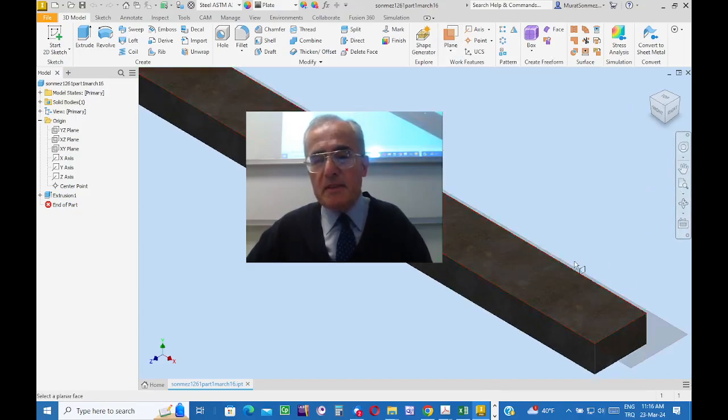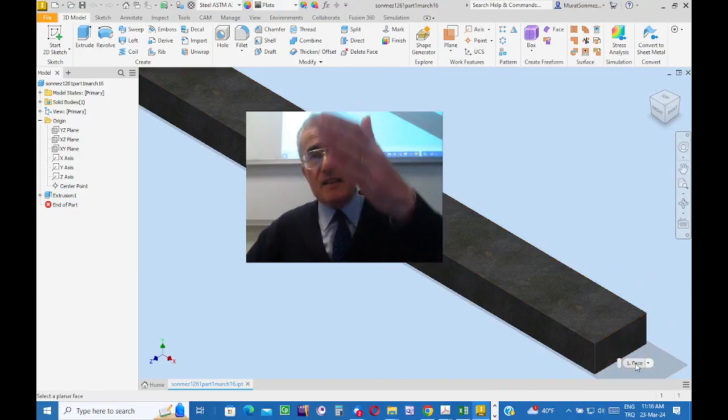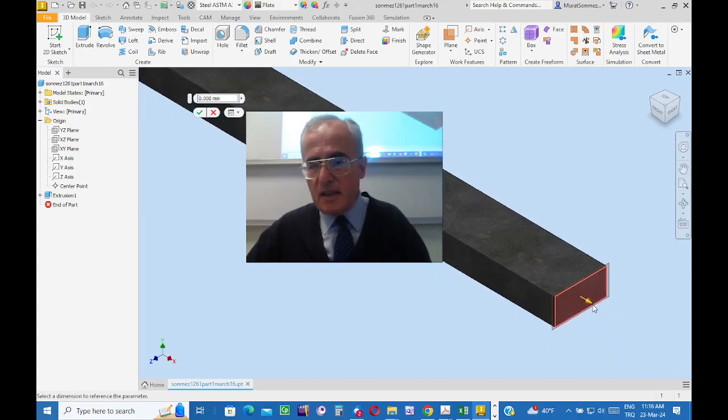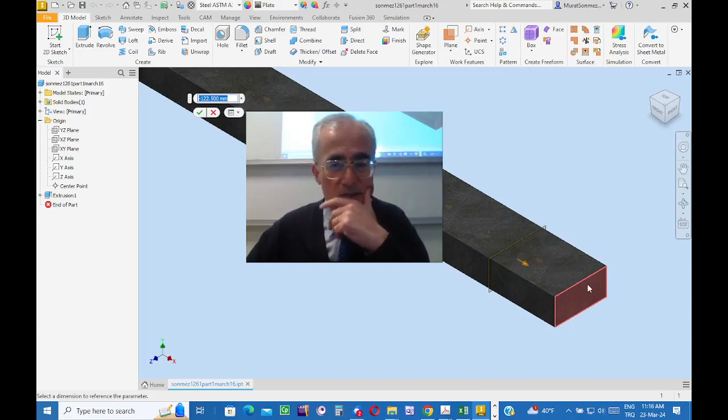Now, to be able to split the surface, I need to have, like a knife, a plane. It should be perpendicular to the surface. I indicate this surface as the reference. And then, the work plane is to be over here, like a knife, to split the surface for having such a portion. Well, from this window, I see the coordinate of the work plane, if it is to be at that side, relative to this reference, is negative.